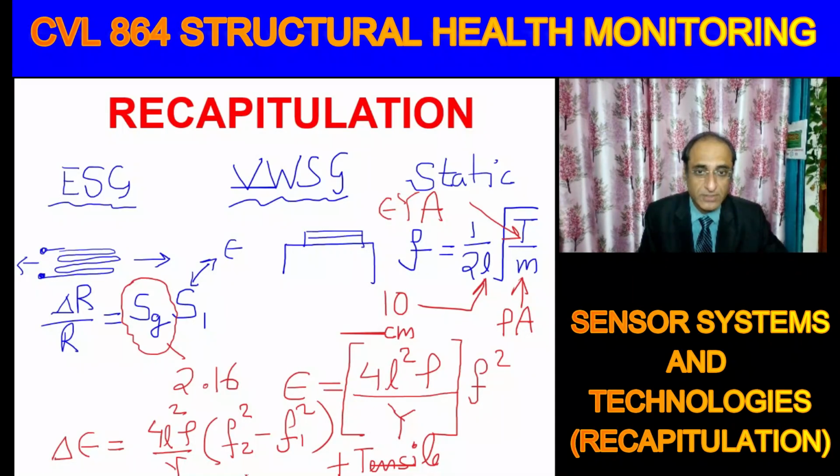So no doubt. So what is the value of R? We know delta R. R is for the electrical strain gauge. The value of R was noted by you. If you recall, there was an initial value. See, the ideal value is 120 ohms, but the value which we noted was up to 3 decimal places, a total of 6 significant figures. So our value was something around 120 point something, I don't recall.